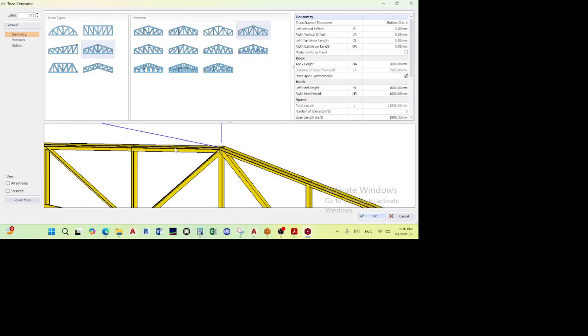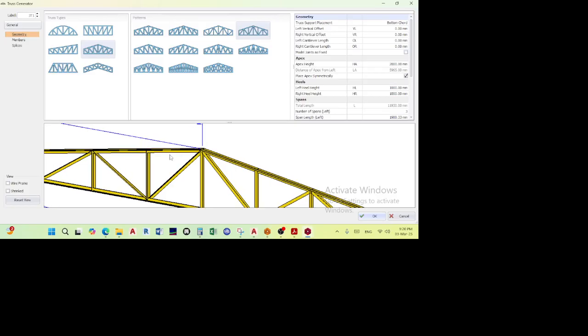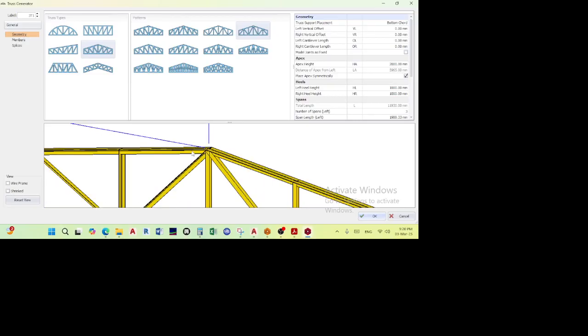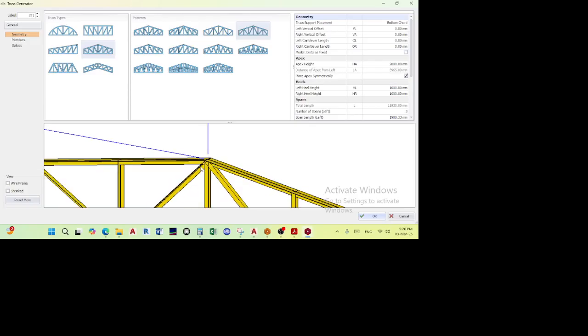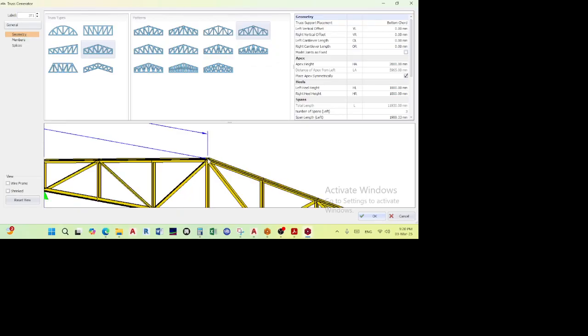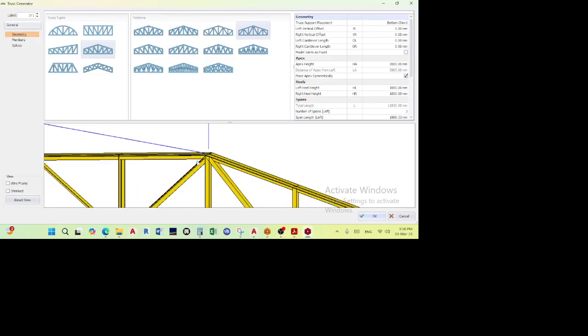Also, another thing that I would like to advise you guys: read as many structure drawings as you can, or read as many design codes as you can, so that you get a general idea of what these truss members are made up of. The ones that I've seen usually, because of serviceability, a structure like that one, you're only going to be accessing the roof if you need to maybe repair it, right? But if you're going to be accessing it for other reasons, maybe if you intend to put heavy things like maybe a geyser or maybe air conditioning, exactly. So maybe then, because of the dead load, you would want to have stronger members. So for me, I'll just use an IP200, right?